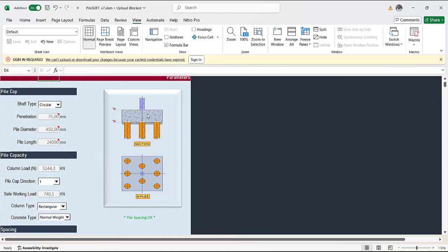The pile cap is just to take the load from the column and distribute it over some piles and also onto the soil, because you would see that most of the time the pile cap sits not only on the pile but also on the soil. That simply means the load from the pile cap is usually distributed onto the pile and onto the soil, but majorly onto the pile.